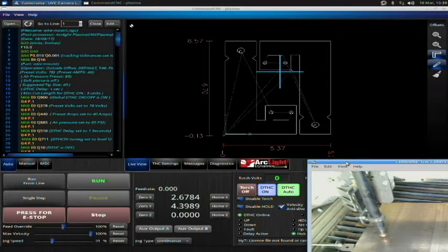If you try to cut a part with, say, 65 amps with an 85 amp tip, you will not get good cut quality. Okay? If you try to do vice versa and cut 85 amps with a 65 amp tip, you will blow the tip out because it's too much power for that tip. So each tip is specifically designed to give you the best cut quality on that particular part.